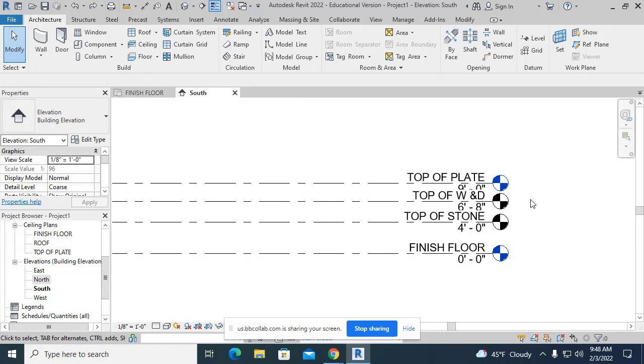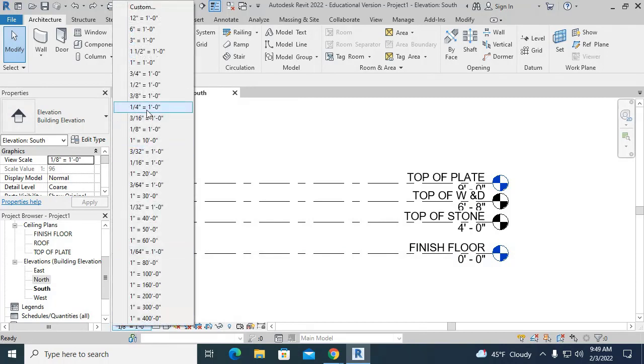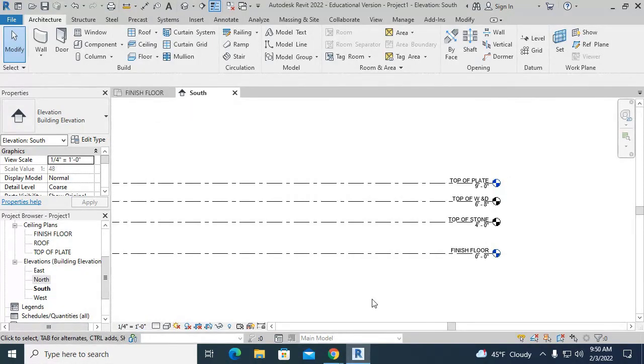All right? So what you're going to do, let me press hide here, come to the scale, click, and change it to 1/4. So there's 2 types of text on drawings, 1/4 and 1/8. Always. Once it's on paper, it should be that high, 1/4 and 1/8. See how it automatically changed when I changed the scale?